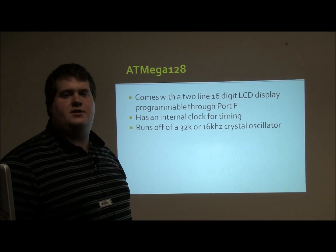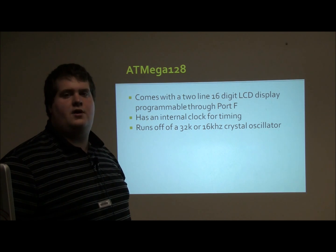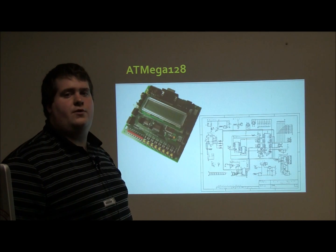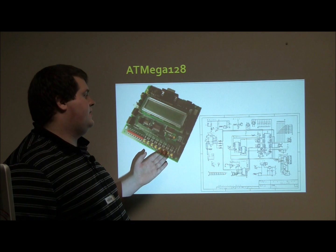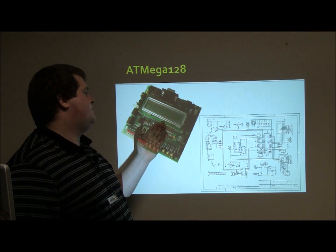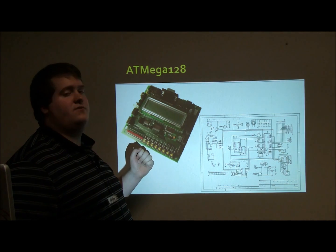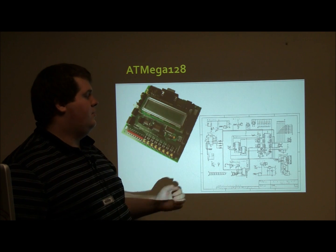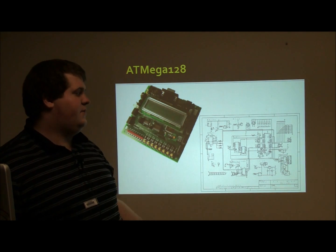It also has an LCD screen that has 2 lines of 16 digits that's programmable through port F. It also has an internal clock that runs off a crystal oscillator running at 32 kilohertz and 16 kilohertz. Here is the ATmega 128 on the PCB provided by the TechBot store. There is the LCD display that comes with it that we will not be using for this project, and the several ports that it has already included with the schematic of the whole PCB.